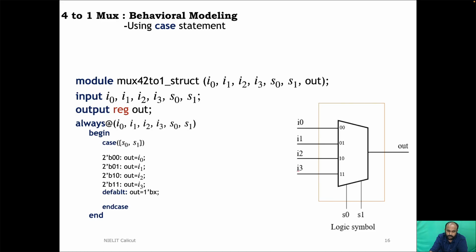Here you may understand the importance of giving 2'b, because if you are not giving 2'b here, this 10 may mean ten, because the default base in number system is decimal. So it's very important that you give 2'b so that the compiler knows clearly that it's a 2-bit number to expect from the input, and it should be in binary format 10.